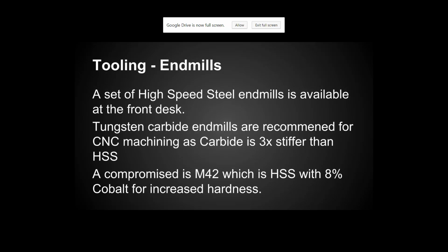High-quality high-speed steel will be equivalent, if not better, than M42, but even cheap M42 is still better than our bargain basement. Can the material harden during the milling operation? Yes, stainless steel can work harden itself during milling operations, so you typically want to move as fast as you can. So the harder, the stiffer the tool, the better it is for the material itself.